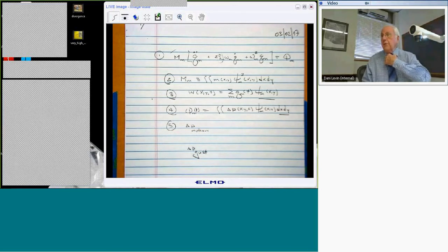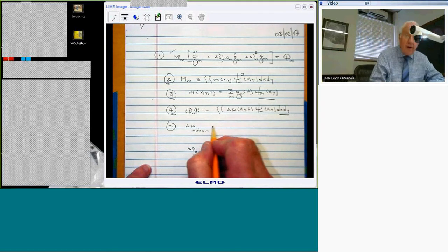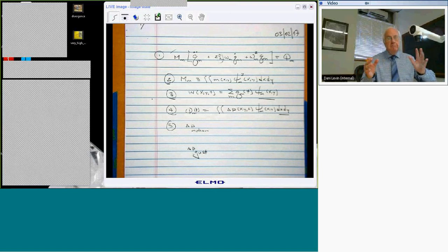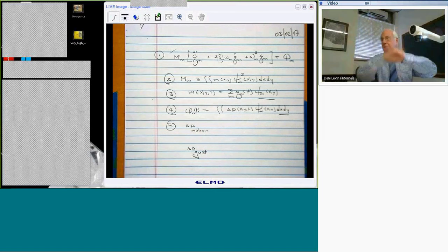And to simplify things for the moment, we're going to assume that the Mach number is high enough, a supersonic Mach number, that we can use something called piston theory. And for those of you who are hanging in for the last half of the course, we'll talk about where piston theory comes from. But for the moment, think of it as some aerodynamic friend. You have structural friends, you have aerodynamic friends. In this case, it's an aerodynamic friend that tells you this is the thing to use at high supersonic flow. High meaning Mach numbers 2 or greater, but not too high. If it gets up to 10, then that's hypersonic flow, and you have to do something else again. High, but not too high.